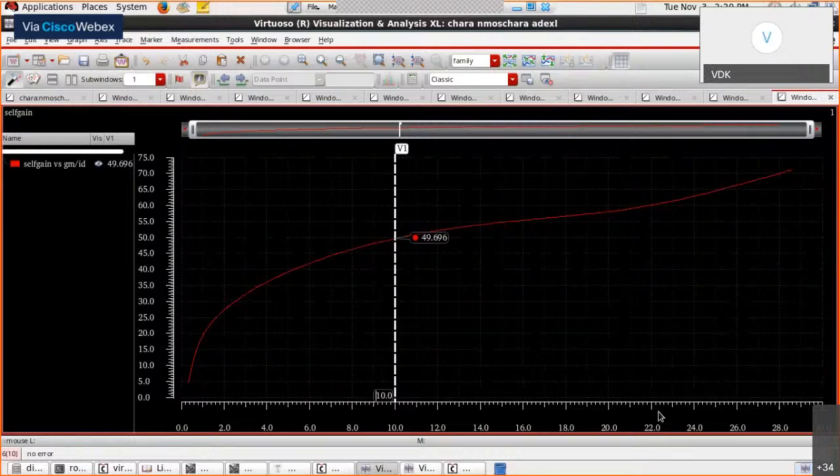We prefer to work amplifying devices in weak or moderate inversion because we get large GM at a lower power dissipation, by using a smaller value of ID. Hence, we hike the GM by ID value from the required minimum of 3.3 to approximately 10.